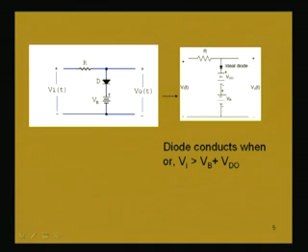Now, in this case, you find out the condition when the diode will be conducting. Vi is sinusoidal, it varies with time up to a peak value, it will be increasing then decreasing to the negative peak and it will continue. So, at any instant, to know the condition for the diode to conduct, we must see when this P is at a higher potential than N. So, we are applying the voltage Vi.